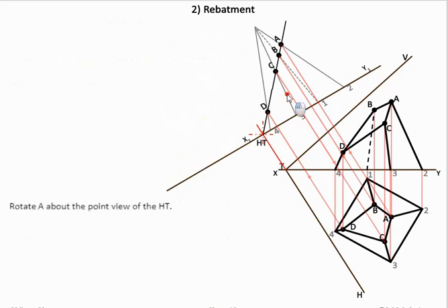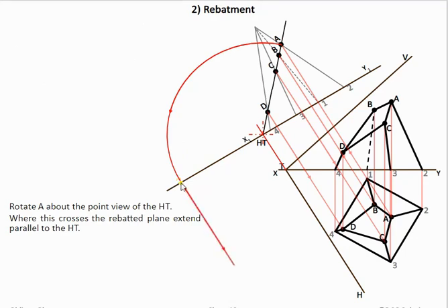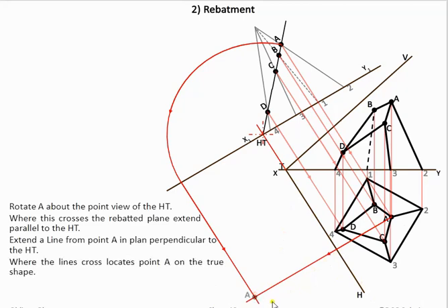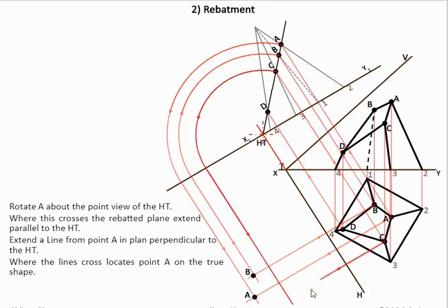So we take point A, rotate it onto the ground. We have it on the ground here. And what we're going to do is bring it straight down here, and from A here, bring it out 90 degrees. Because it's folding out along HT as well, like a hinge. So that's point A found, and then point B is found, same method, point C, and then point D. So this method is used when we have the auxiliary already drawn, and it's an easy method of just rotating this flat onto the ground, and that's how we get our true shape in this question.